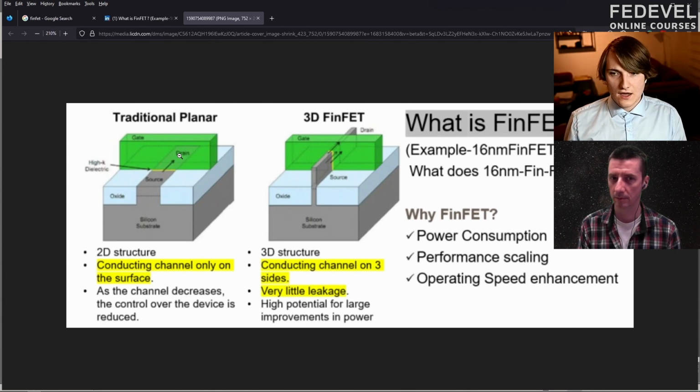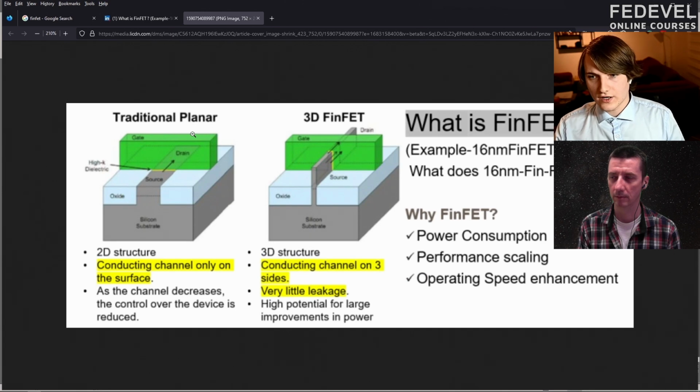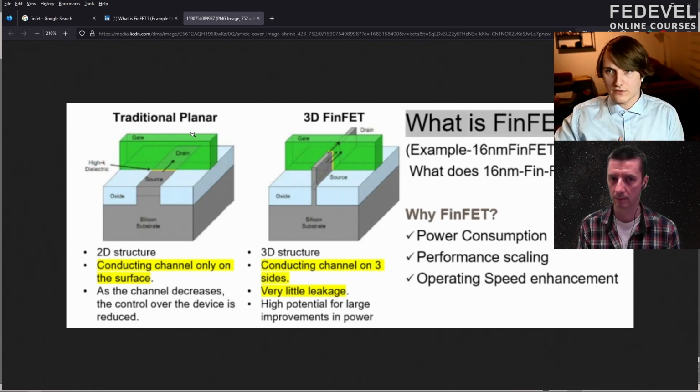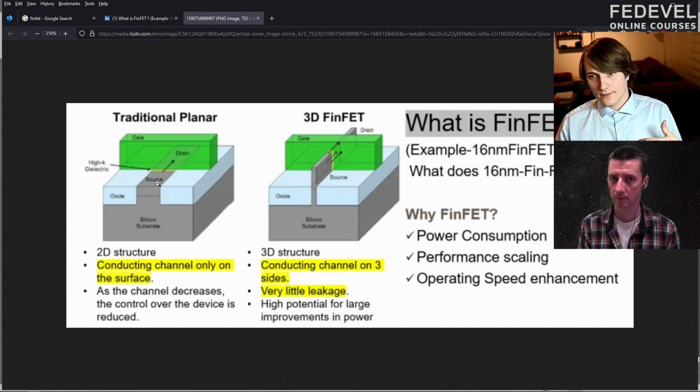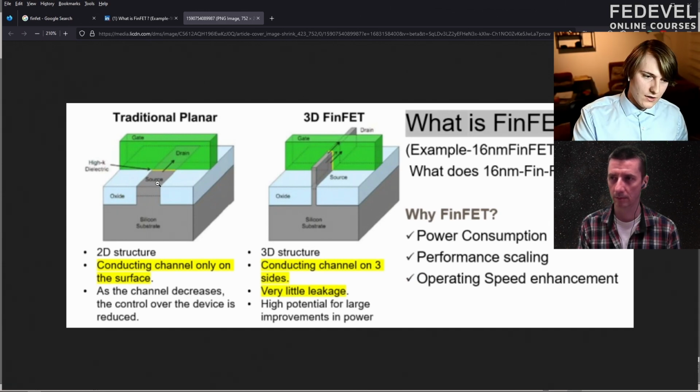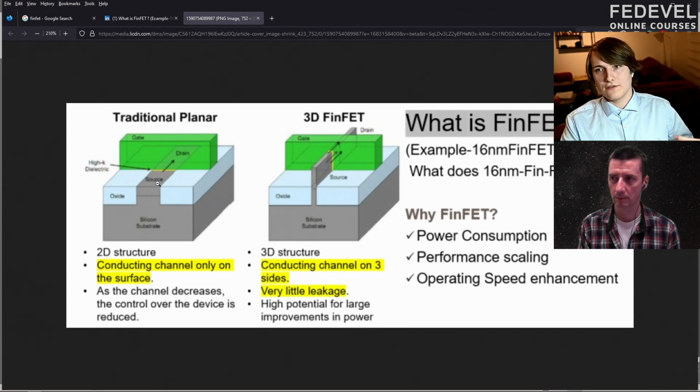And this is actually a huge part of the power consumption of a CPU. It's just the fact that whatever you do, there's current flowing from the source to the drain. And if you have multiple transistors on top of each other, it just flows from the supply to the ground. This is what they call static current or leakage current. And the only way to make that better is by making your gate longer. But you don't want to make your gate longer because then you can't fit as many transistors on a piece of silicon, and that's the thing that drives the speed.